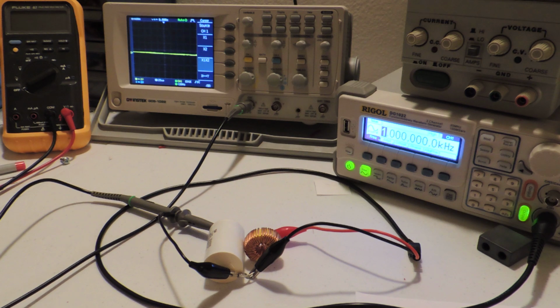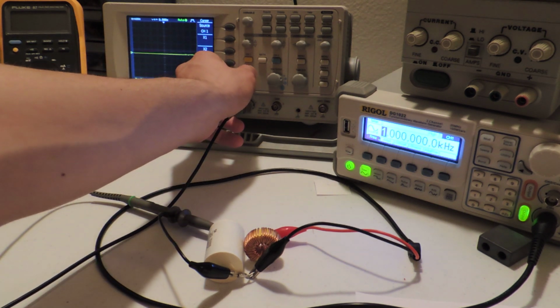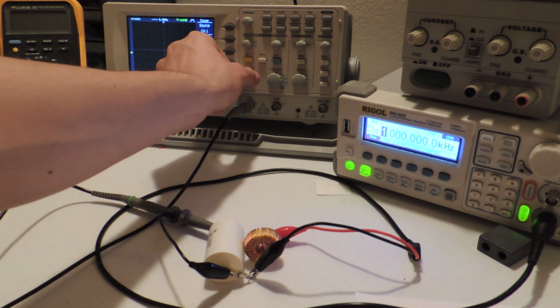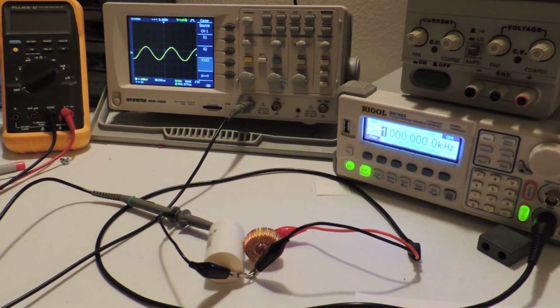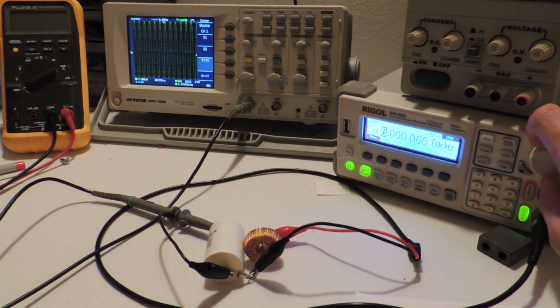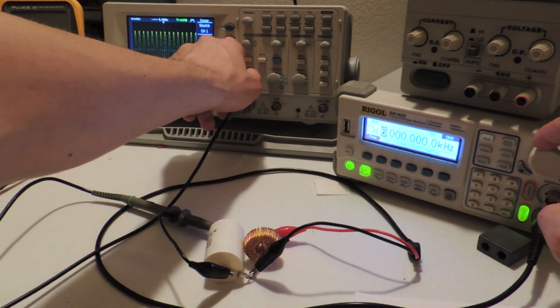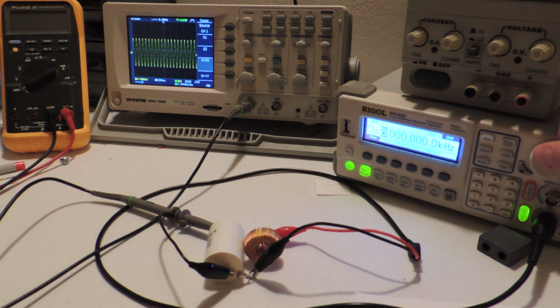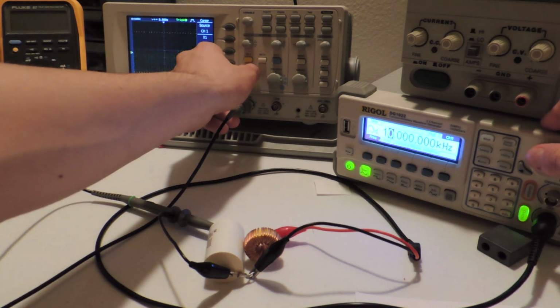Now that the two are connected, we can see that there is some signal on the scope here. So we will adjust it and bring it down in amplitude. Now we will slowly start changing the frequency. As you can see, taking the frequency up increases the amplitude. We will continue to increase the frequency until we reach a point of roll-off, meaning that as you go up in frequency, the amplitude reaches a point where it starts growing slower and slower for each increase in frequency, and eventually starts rolling off in the opposite direction.